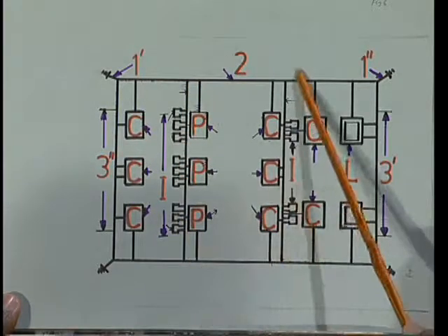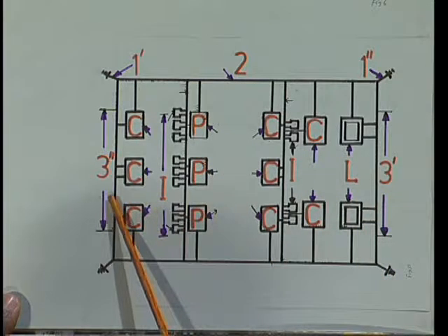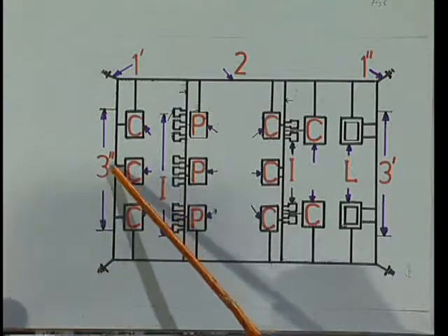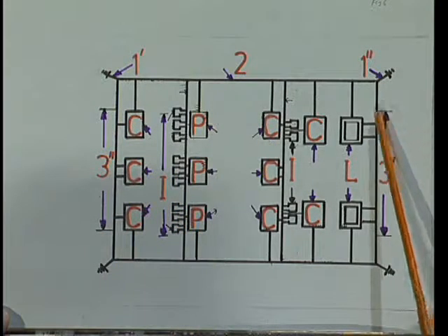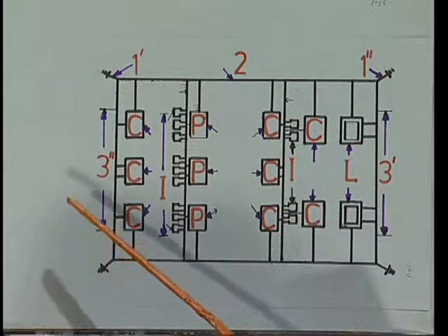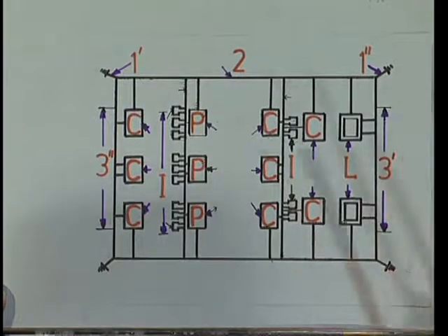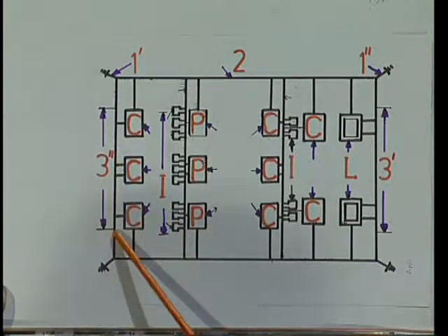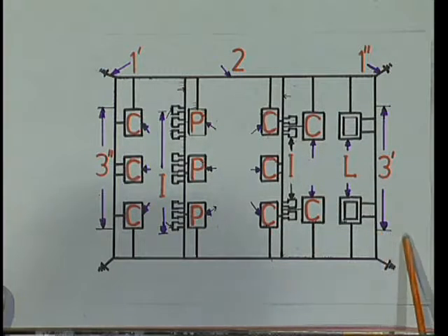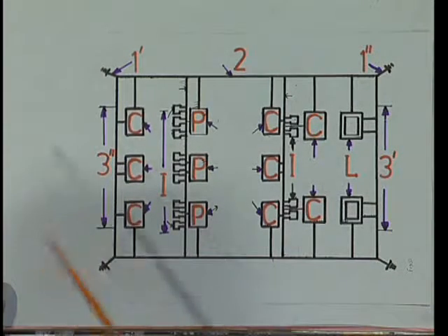This is another earthing network. Here also we provide earthing networks, but it is not shown because of clarity. Third one is these overhead earth wires coming from the towers, with towers on this side and on this side also. So earth conductors come like this and are connected to the earth ring. Similarly, on this side also earth wires are connected, and these earth wires are connected to the tower.